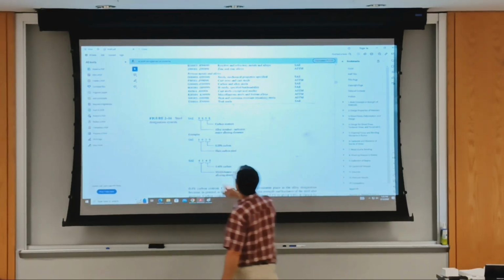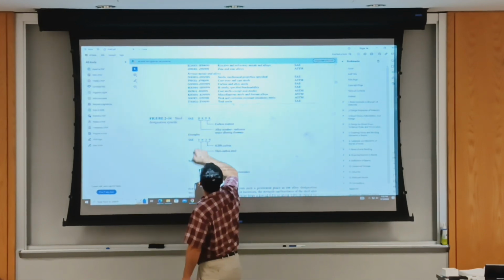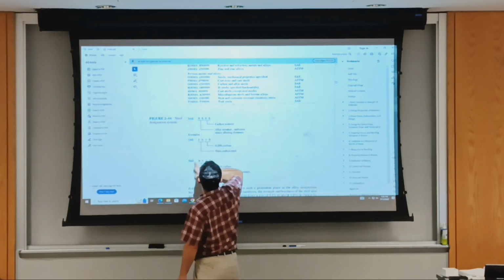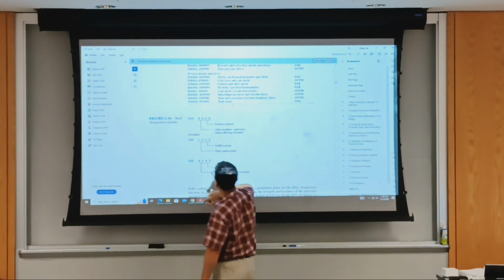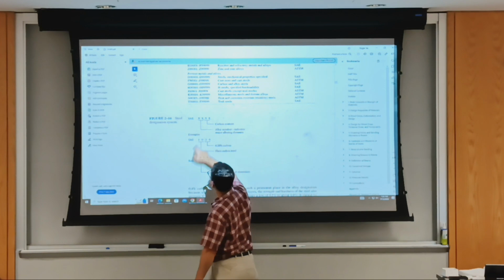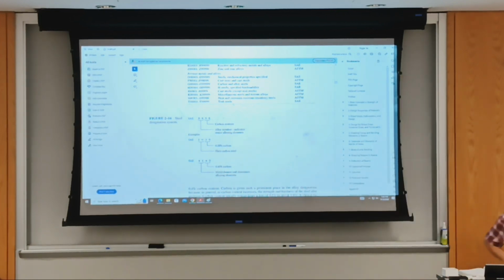And so the 4-digit designation, this is the carbon content, and this is the alloying number. 1 and 0 in the first 2 digits is indicative that there's no alloying element. You can see here molybdenum and chromium, the first 2 digits are 4-1.